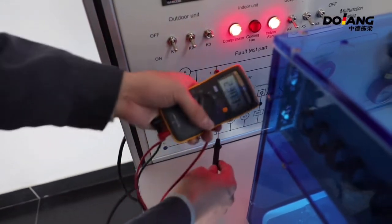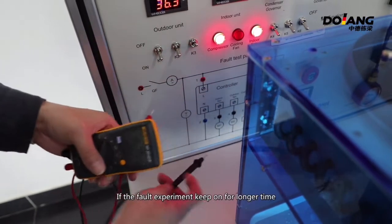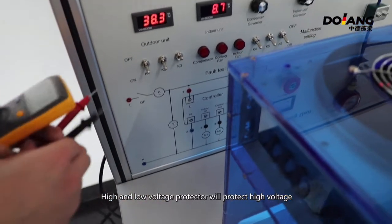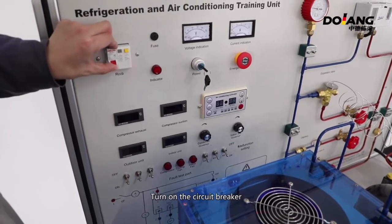The voltage is normal here. Controller voltage is normal. If the fault experiment keeps on for a longer time, the high and low voltage protector will protect against high voltage. Press the button of the high and low voltage protector to reset.